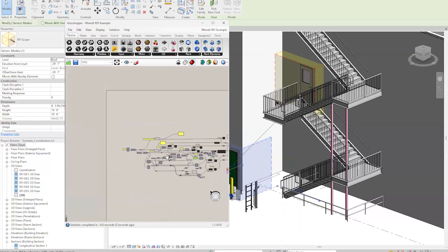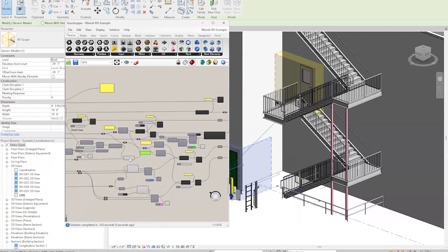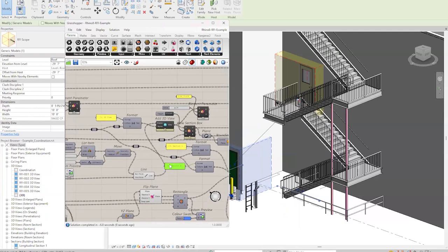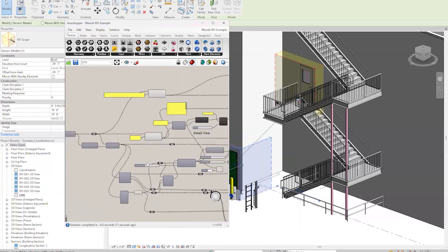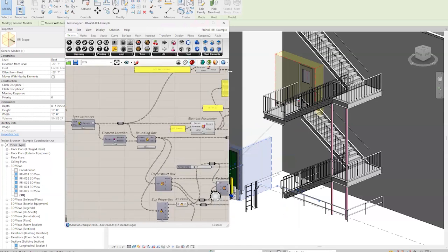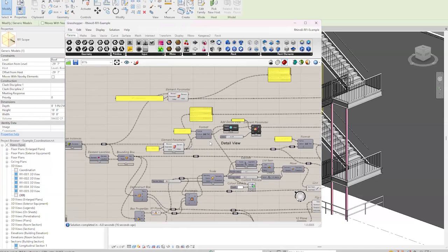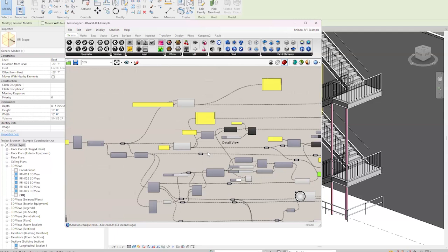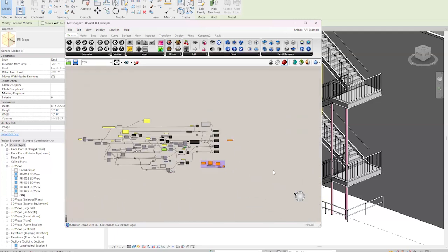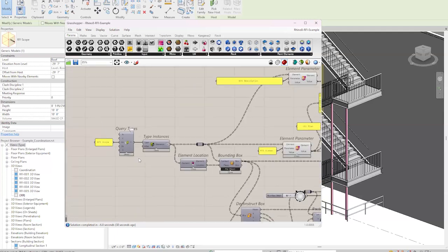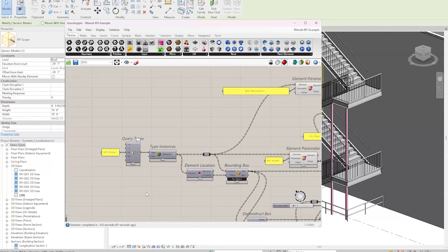What I'm doing here now, this is getting a little spaghettified, as we say when we get a lot of wires going around in a Grasshopper definition. Now that we're in Rhino 8, we have a lot more components to help. You can break up your Grasshopper files, so you can do one part in one file, one part in the next. Similar to how you could do in Rhino 7 with Elefront. It's a great workflow that keeps you from getting absolutely monstrous definitions that are hard for other people to work in. Kind of like creating functions, right, in other programming languages.